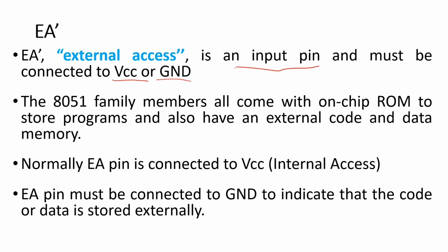When we consider 8051 family members, all those with on-chip ROM used to store the programs, and also an external code and data memory, come with this EA bar pin, which is normally connected to VCC.